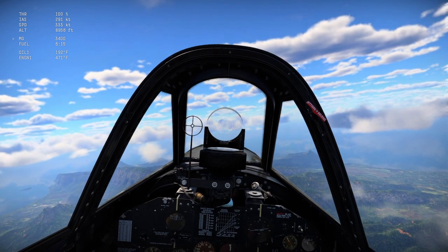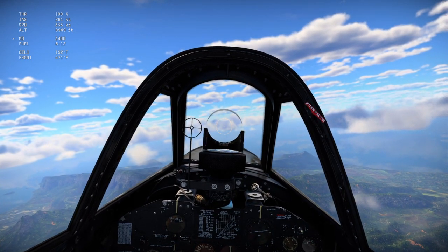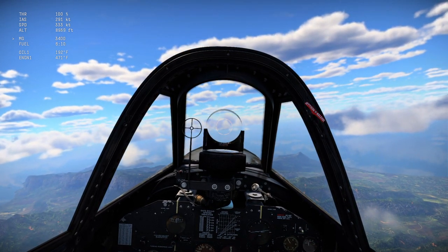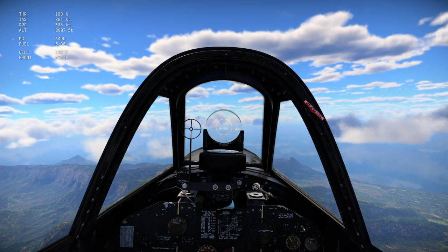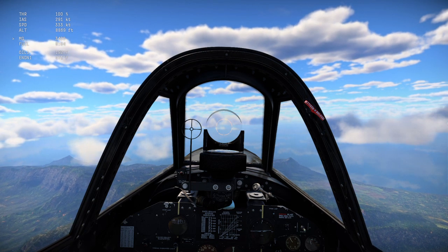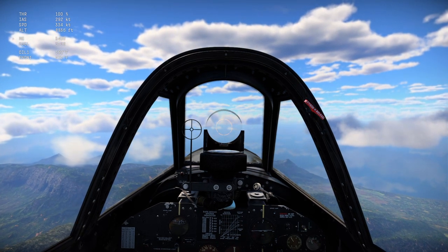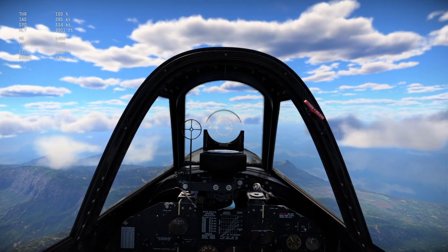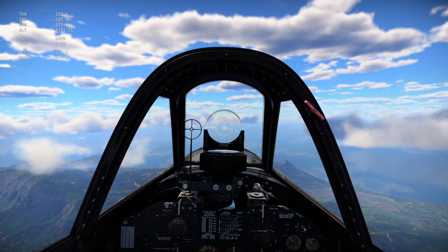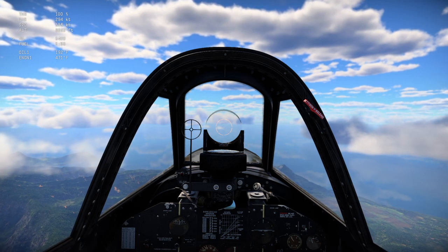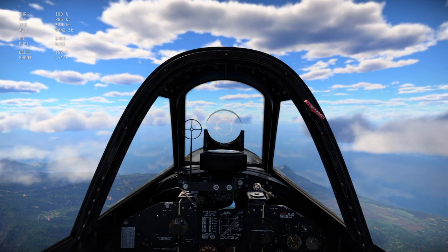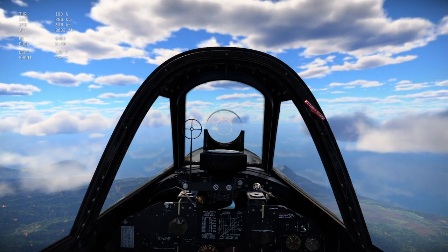There are a few aircraft that have this in game. It's mostly the P-51, so anything Mustang series. Yaks, LaGG-3, G.55, C.202, C.205, and the Ki-61, I believe, also have the Meredith effect, but nowhere near as much as the P-51. P-51s were literally built to be fast, so that's why they have the Meredith effect. They were literally meant to have it. That's why they're so fast.